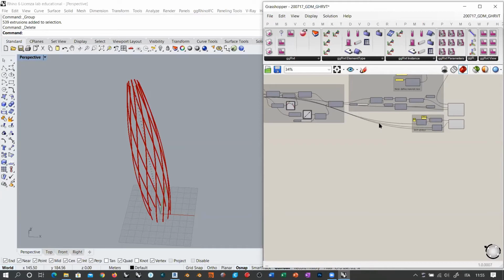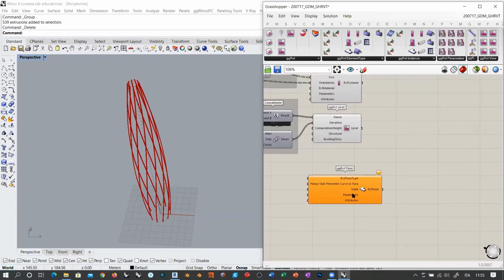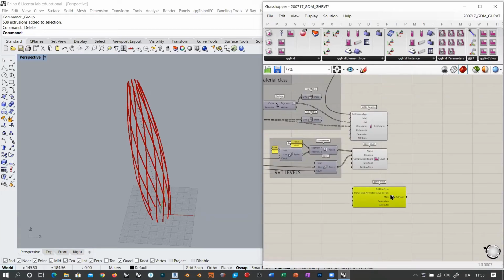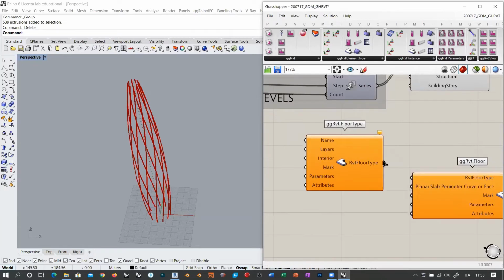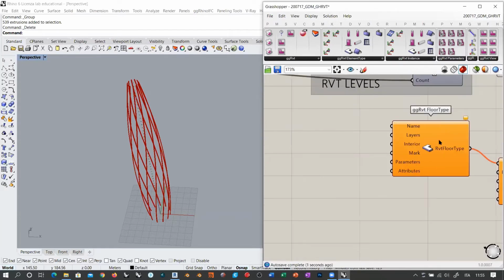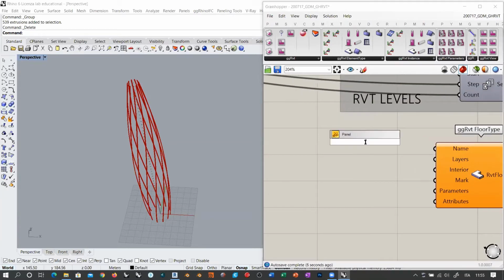So, first of all, as always, instance. Revit floor is going to be the instance. It's going to be the last of the implementation. So you see column, level, and floors. And now, floor type. Let's go into element type, grab the floor type. You can already connect it. And now, things here are a little different. Name: let's call this something like my floor. This is typical of programmers. Normally they add my nice floor. I don't know why, but anyway.